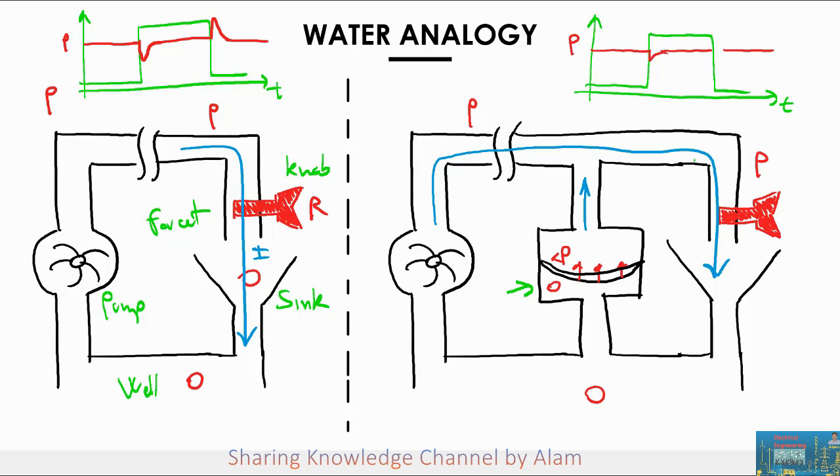And the same can be said as far as when you close the faucet: the amount of overshoot of the pressure will be much smaller now. The simple reason for that is that you have a storage of energy, in this case pressurized water, sitting very close now to your sink, and the moment the pressure decreases at your faucet for any reason, this device will automatically inject or take in an additional amount of water, trying to compensate and to keep the pressure as constant as possible.